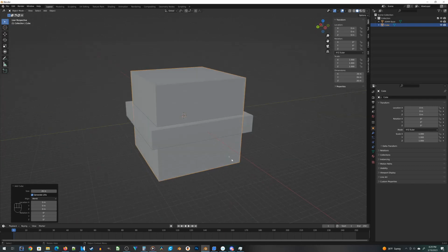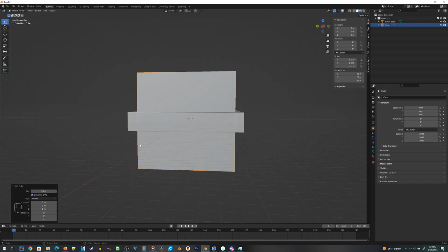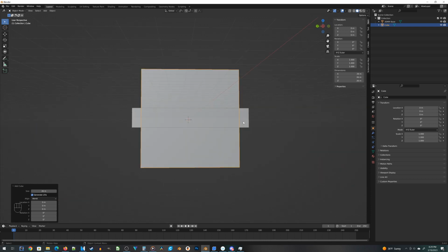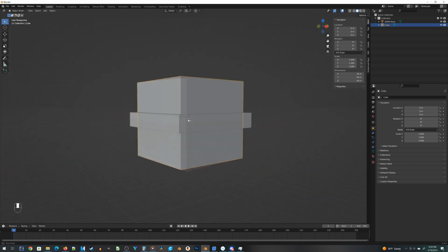At the moment here though, the base that we're going to cut out kind of goes through the entire thing. I don't really want to do that. What I need is that a Games Workshop base is approximately 3 millimeters thick. So I just want to cut down 3 millimeters into the top of the base and leave a little bit of material down here to hold the entire base together as one piece. Here's how I'm going to solve that problem.